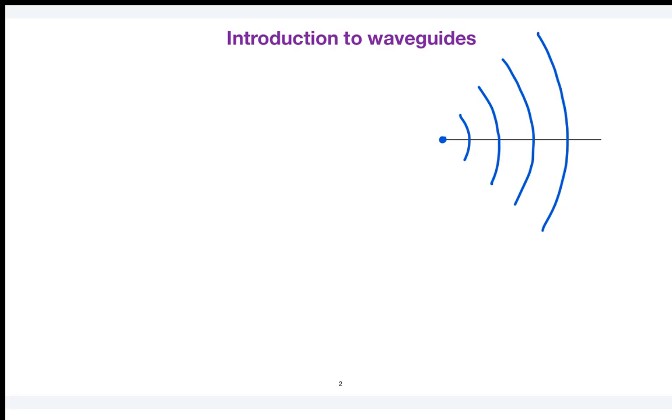The main thing, when I summarize here, is that waveguides are used at gigahertz frequencies. And waveguides are used basically to maintain a uniform power density throughout the distance. You can see here there are different types of waveguides. Parallel plate waveguides, I have just seen. But you can see here, as the wave tries to propagate, it is going to expand out in all the directions.